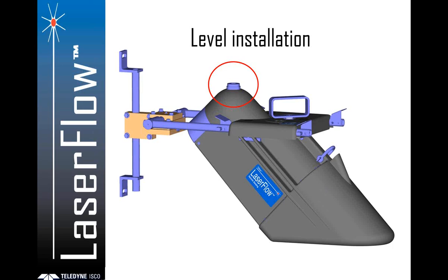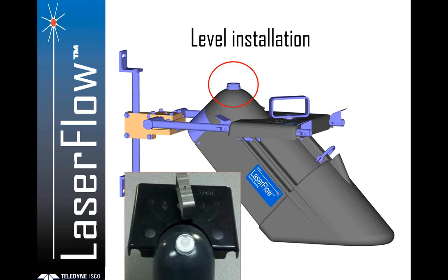to your screen. So as you're doing your level adjustments, if you're doing it from up on the surface and can't see this bubble level, you can actually see the pitch and roll on your computer screen or on the LCD of the meter. Some more close-up views of that.